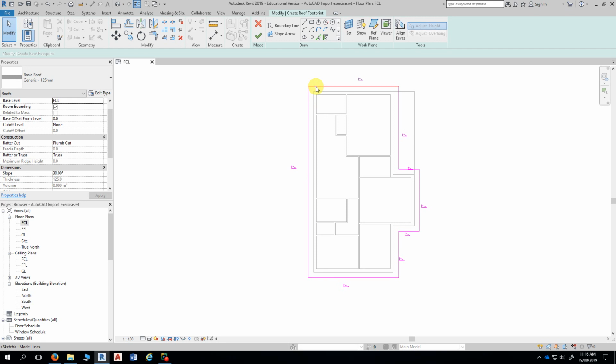So do a cross box. Quicker than that? No. There's a key on the keyboard that starts with T, tab. Tab, yeah. So if I mouse over this first one here, I'm not selecting it, so mouse over it so it pre-selects, hit the tab key and release it.